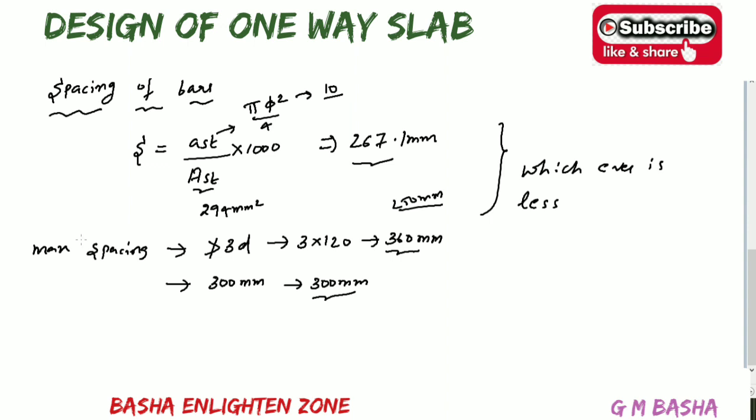So finally provide 10 mm bars at 260 mm center to center. The minimum spacing here is 267, but we can't keep the spacing in odd digits like 267. So I am limiting to a lesser value, not approximating to a higher value. Don't go beyond 267. Here I am mentioning 260, or else you can take 265 mm, but don't go beyond that. Limit to an easy value like 260.